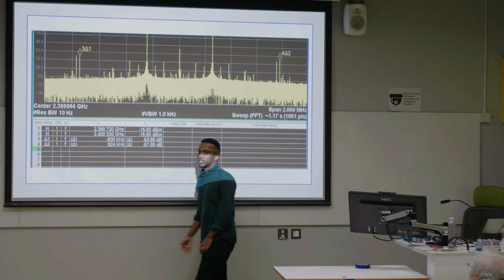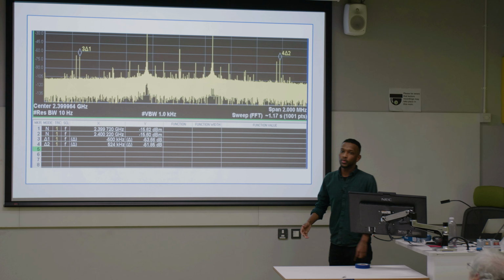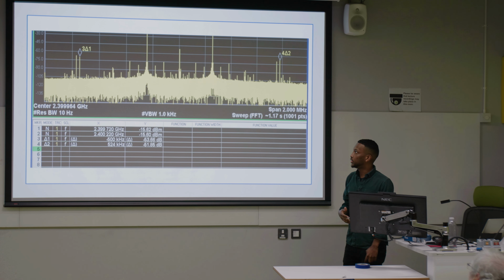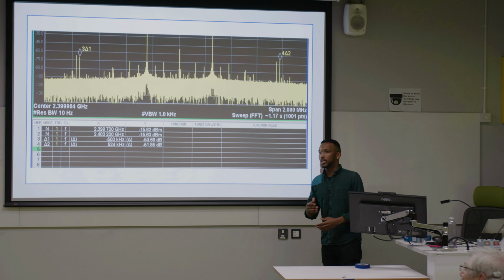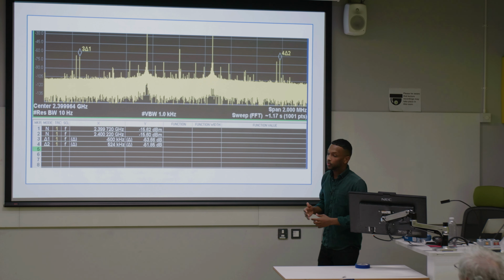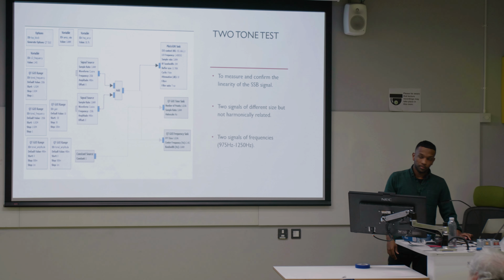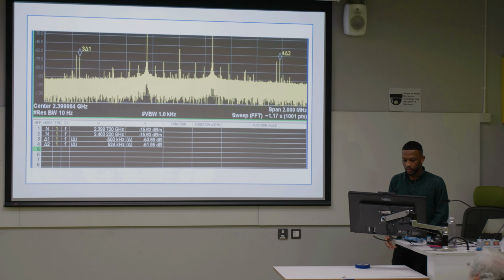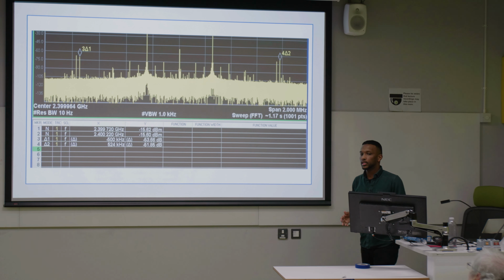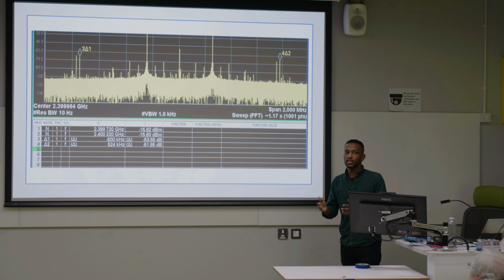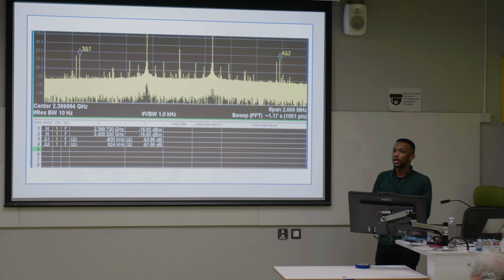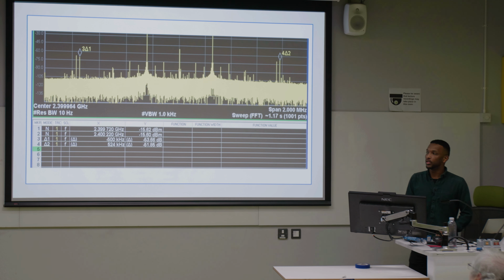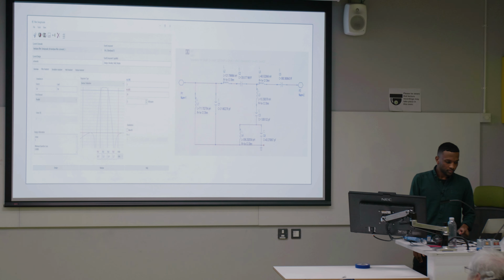That made it hard for us to actually spot which one is our harmonics and which are the noises. So what we did is change the amplitude within GNU Radio, and we could see that some of the signals are actually moving with the amplitude. This tells us, okay, this is the noise, and it helps us differentiate between the unnecessary noise and the harmonics that we need to study.